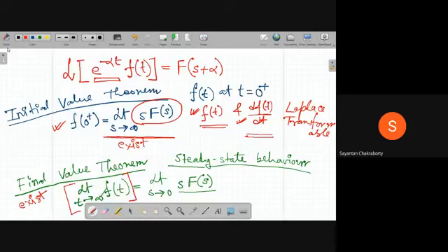So I think you have the concept of poles of a system or roots of a characteristic equation. So this theorem will only be valid if the roots of the characteristic equation or poles of the system lie in the open left half plane. Yes, sir. Open left half plane. Okay, so what does the open mean? What does open left half plane mean? Left half s plane is fine. Obviously, this is the s plane. It is to the left of the imaginary axis. Then what does this open left half plane mean?